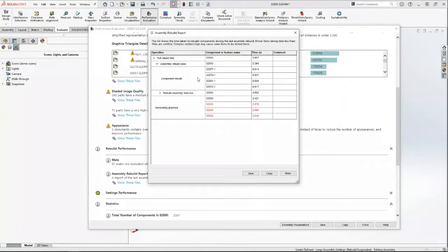So in this case, remember, ideally, when you do the rebuild, it shouldn't be going through every single feature of the components. But this is probably one where you narrow down and see, oh, is there, for example, something that's causing these to, maybe I open them lightweight, right? Maybe they're opening up resolved. And then from there, I want to figure out, well, what's causing them to open up resolved? Because later on, you'll find in the data structure, you'll see exactly why it's taking much longer, because it's loading up more information.